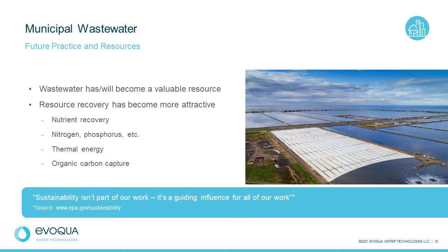There are many valuable components of wastewater, including organics, which can be captured and converted to energy, such as methane and/or electricity, or converted to more valuable organic forms, such as biodegradable plastics or other compounds. Nutrients, mainly nitrogen and phosphorus, which are required for plant and crop growth. Thermal energy is also a valuable component of wastewater, and metals and other inorganic chemicals can also have value. While there are many valuable resources in municipal wastewater, it's the water itself that's by far the most abundant portion, making up more than 99% of wastewater.